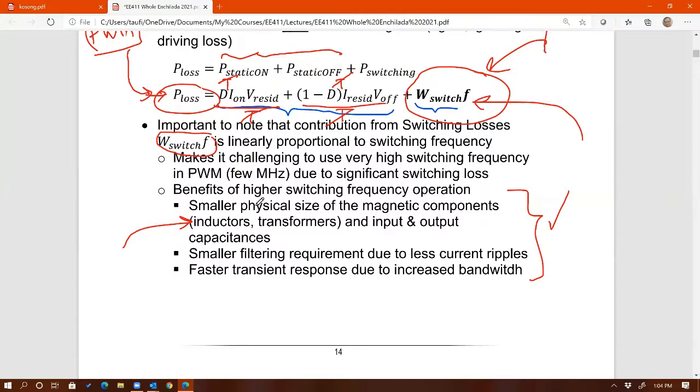Not only that, a capacitor also has what's called ESL, series inductance, and they have a parallel resistance, and all of these are a function of frequency. But how come we didn't consider those in EE411? How come it's just ESR? Well, the answer to that is because the range of frequency that we are using for power electronics does not yet view the other parasitics to be important.